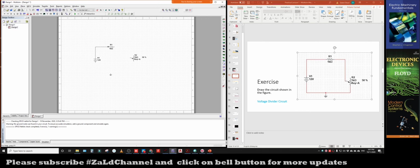And if you'd like to connect to another component, when you reach one of the terminals of the resistor, for example here, just click. It will automatically appear as a wire like this, the right one here. So I have already made the connection between the terminal of the battery and the resistor. All right. Next, you can do the same thing. Connect this to this, or to this. Basically, we want to make this potentiometer work like a variable resistor. Then we connect to the wiper.